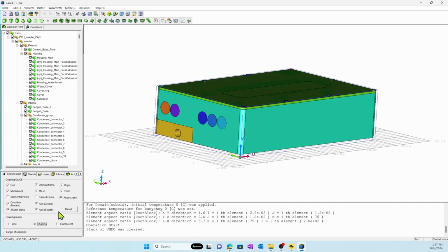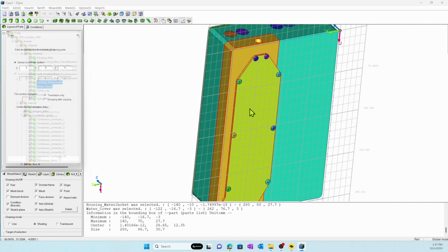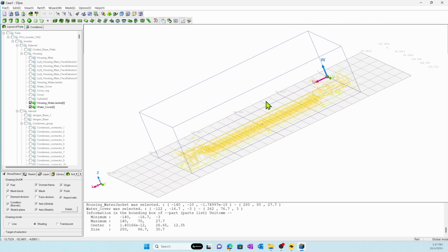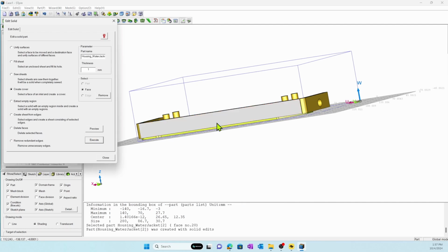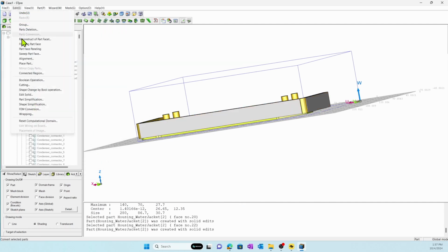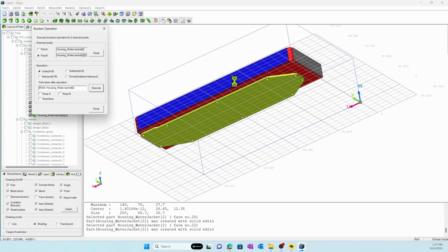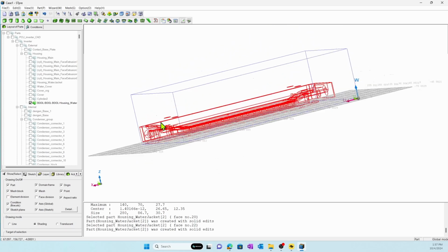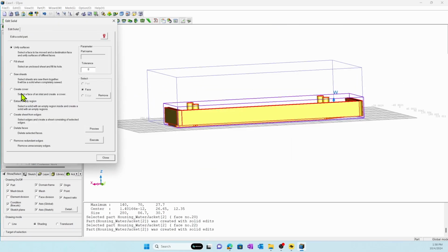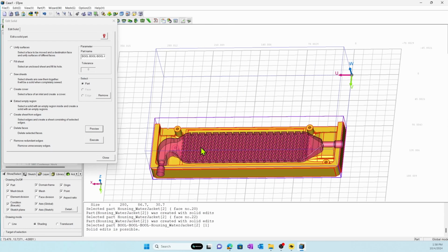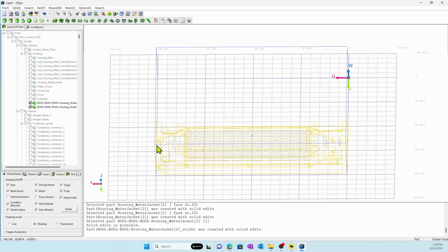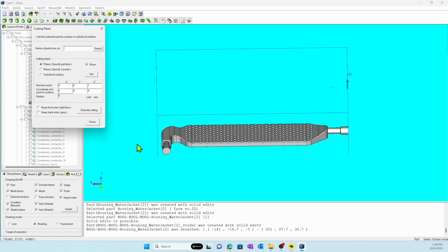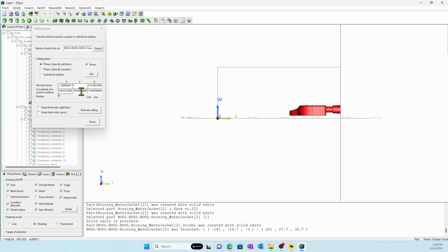This simulation includes water flow in addition to airflow. Let's create a part to set the domain for water flow. We will create this domain by utilizing existing parts, then extract the volume to solve water flow. To set the flow boundary condition, an obstacle part is required, so we will cut the part to create an obstacle part, then register the surface.